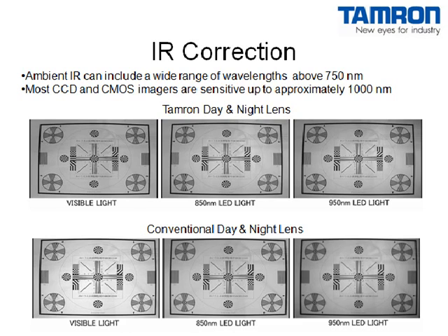If you require a day and night lens for your security application, check to make sure your lens corrects for focus shift across the entire range of wavelengths your application will utilize.